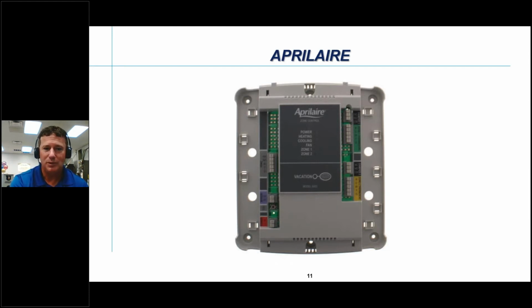But we don't want to use a bypass damper on a variable speed motor for any reason, because we're going to have a swing in barometric pressure on that thing. And we all know what a variable speed blower motor does when it's affected by the external static pressure. We talked about that last week. That variable speed blower motor, as soon as it sees a change in external static pressure, is going to significantly alter its RPMs to maintain CFM.